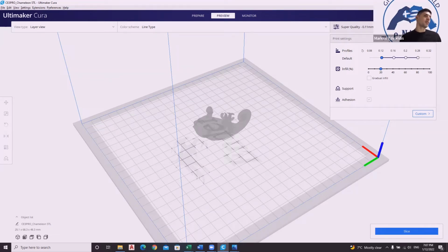Okay, so it means that the step for my printer is 4 here. And I really don't want to change that because I will mess up my stepper motors and my print will not print as good as it would. Keep that in mind. See what the step is for your printer and don't change that.